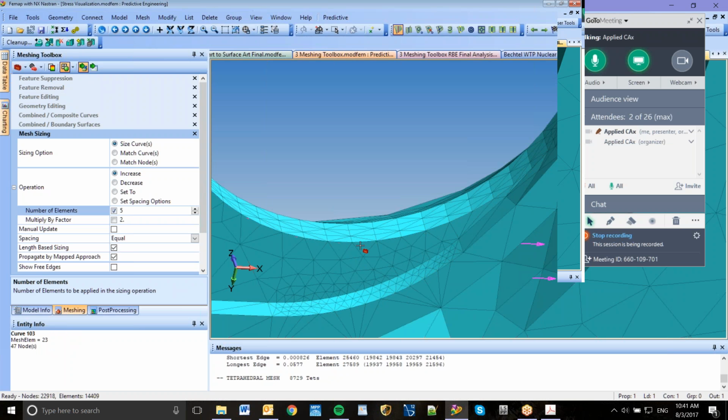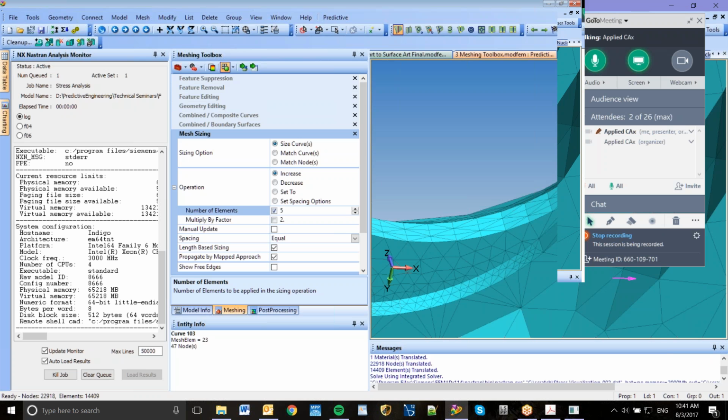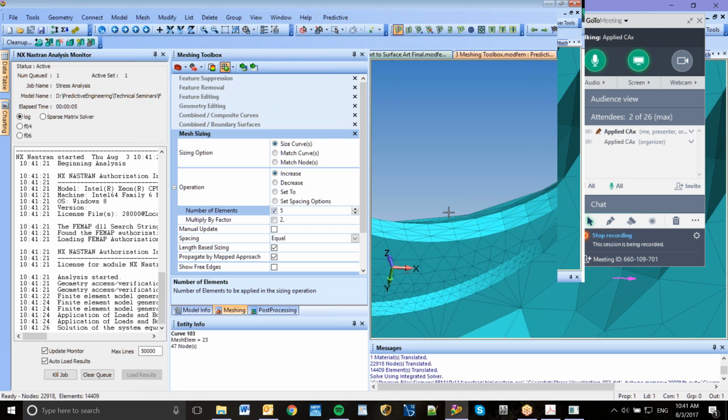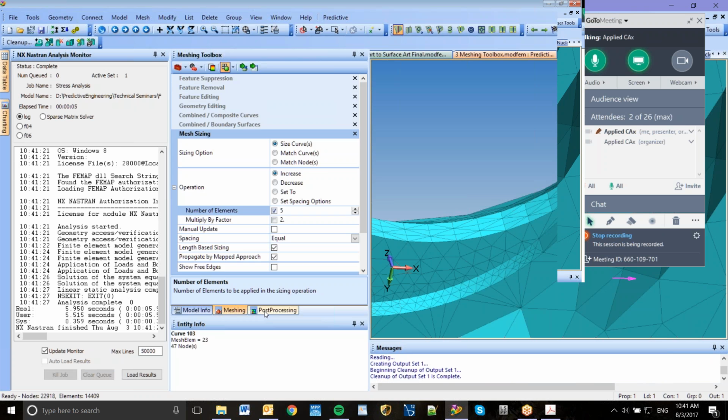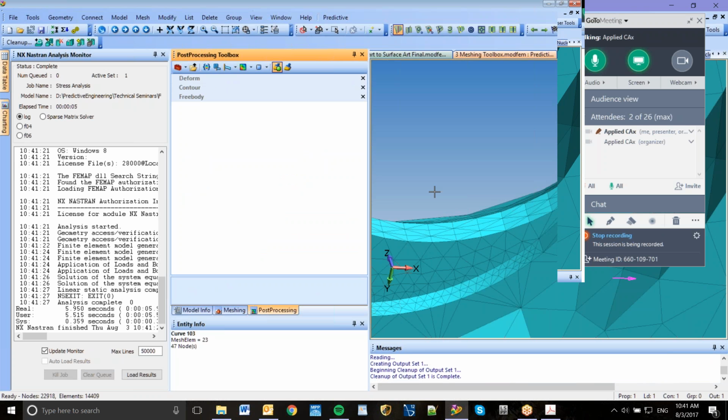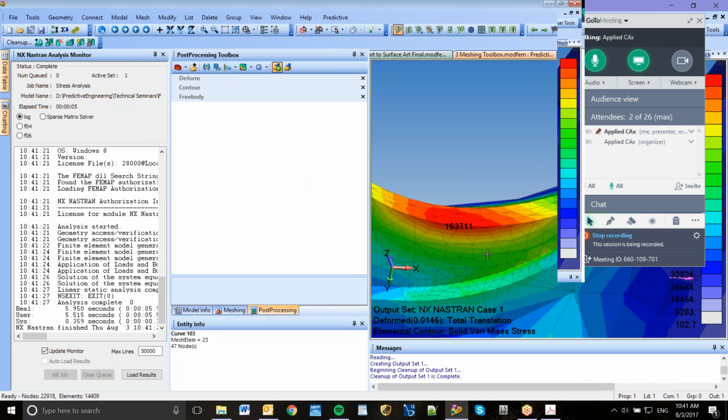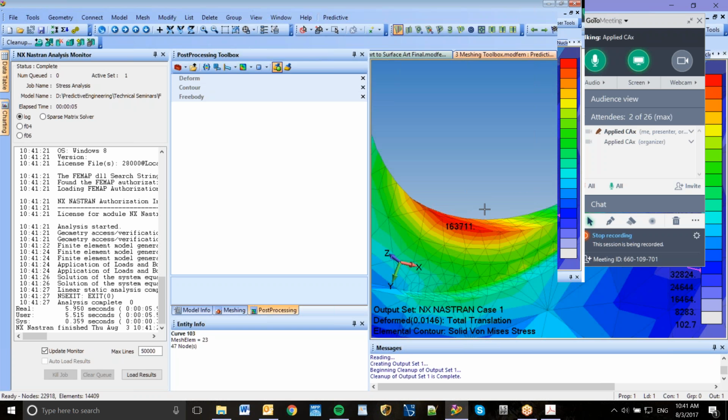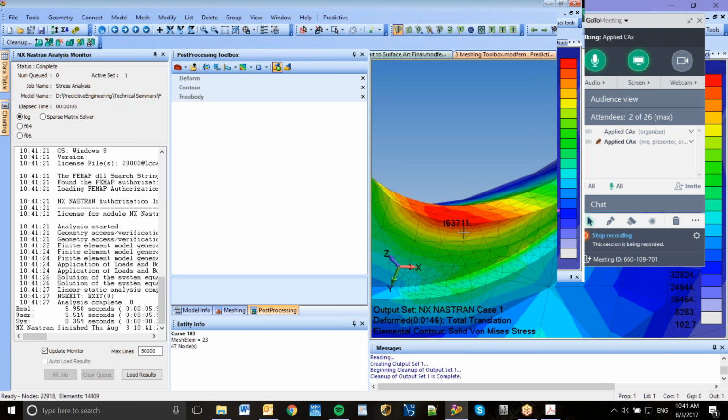So there, I made it. I tried to make it as close as I could, but there's a point where you just give up. It doesn't really matter. If we run this, you can look at the stress. Of course, the stresses will be a bit higher, but you always wonder how much higher. Go back into post-processing, double-click, brings that up. Wow, a whopping 10% more. It just shows you, tets give good results, even when they're coarse.